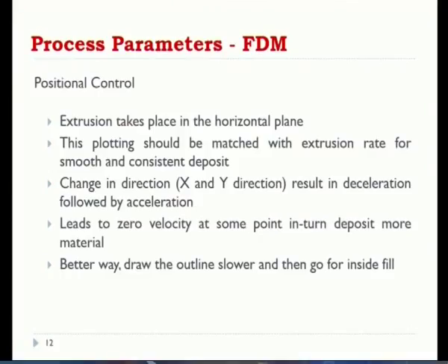And the position control, again this is one of the major area, how to have a proper position control for different layers, right? Mostly how we are laying it up from X to Y or Y to X, right? Say this is how the system is going to work for you. But what may be the problem? Say for example, once starting from X to Y, there may be a small deceleration at the end. Again I am going to lay up Y to X in this way, the zigzag manner. But the problem is particularly at the end of the product, say end of the component, there may be a deceleration. So what will happen if there is a deceleration in the nozzle head?